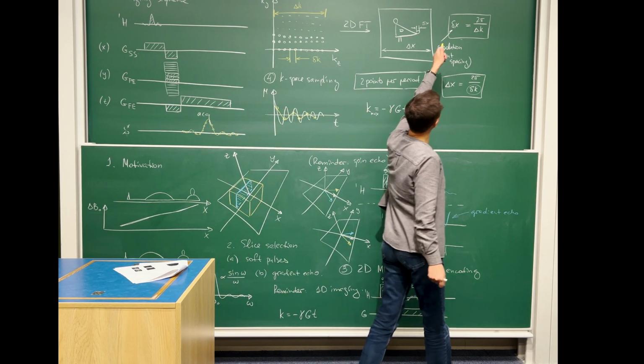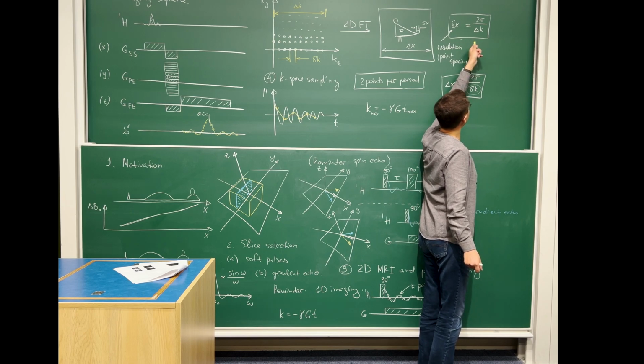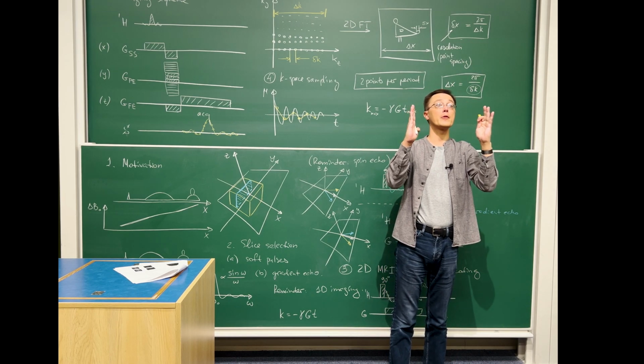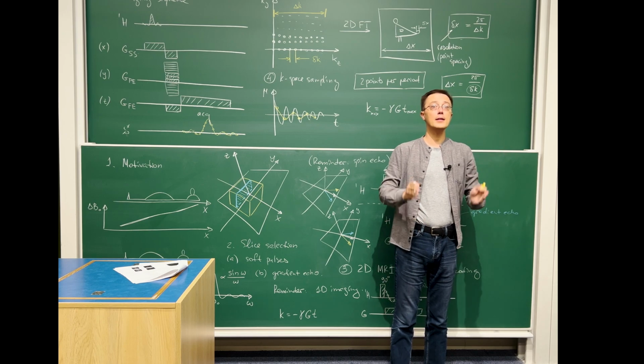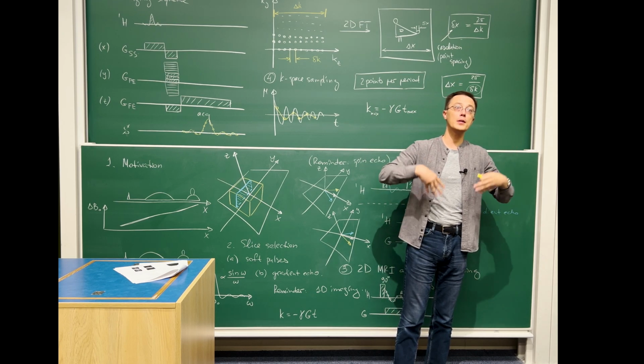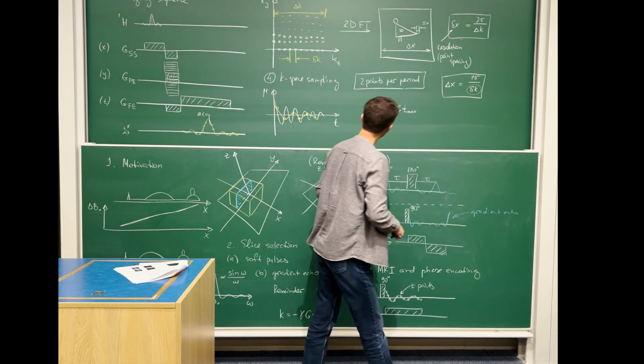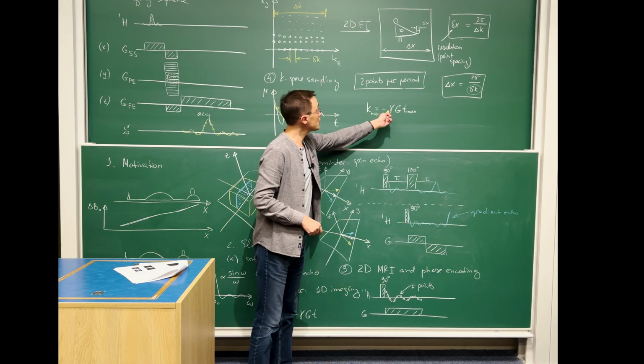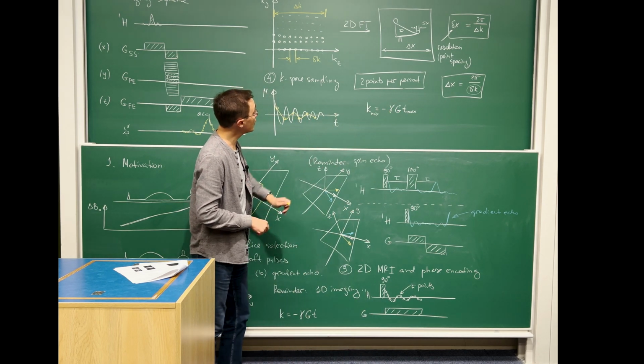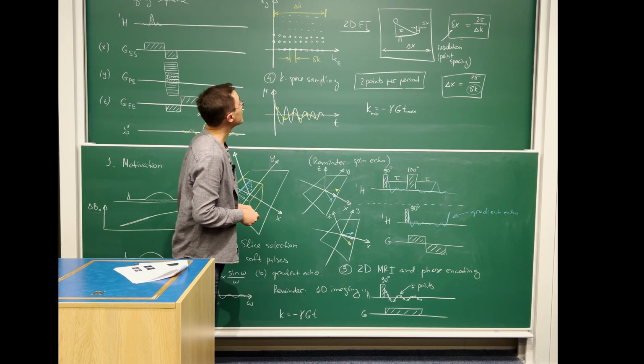And the resolution is determined by what kind of frequencies we can separate. Right? The stronger the gradient, the stronger the separation of the frequencies, the greater the resolution. But there are electrical limitations to do with the gradient strength in there that puts the limit on the resolution.